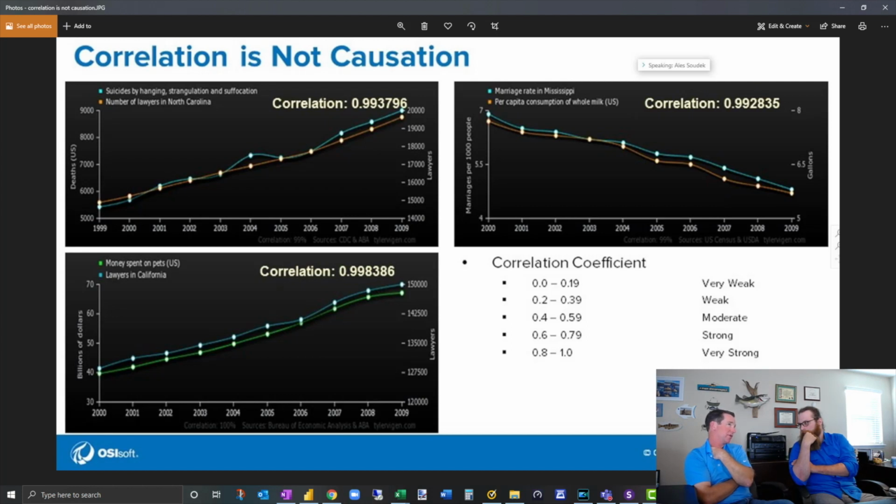That's an average temperature over like a 2 or 3 hour batch. That can make a big difference. You know, I remember early in my career, I was working on a wire winder. They were making multi-stranded wire, like Cat5 type cables. And they said, plus or minus 1 degree on the extruder. If it got 2, 3, 4 degrees off, they would definitely see quality problems in their wire. So there are some processes that are very, very sensitive to small changes. I suspect this will be one of them. And so that is definitely something that can happen.